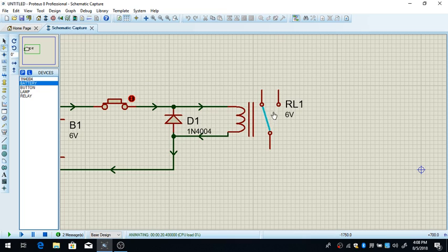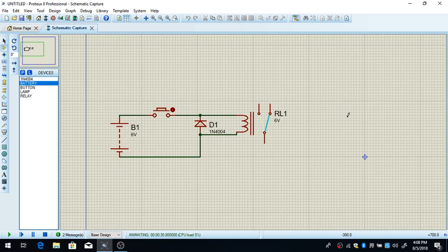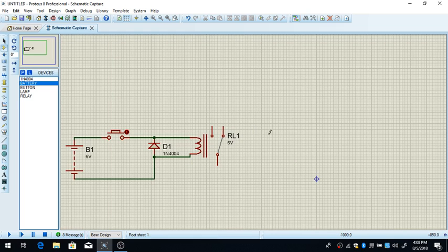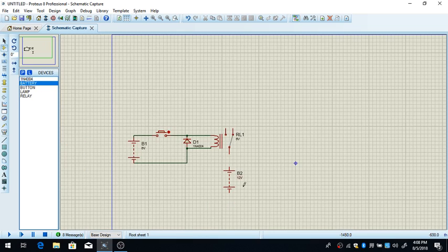So now you have the contact here, and it also depends on what is going on in the secondary circuit that I'm now going to make. So if I open the switch, there is no current, and the metal goes back to the first node. Now I'm going to stop the simulation. Now I'm going to make a secondary circuit. Now put a battery here. You can leave it at 12 volts.